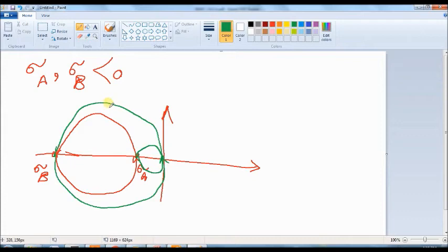So this is the maximum shear stress. You have to see which one of these two principal stresses has the greatest absolute value, because the stresses are negative, and the greatest absolute value is important for us to find this maximum shear stress.